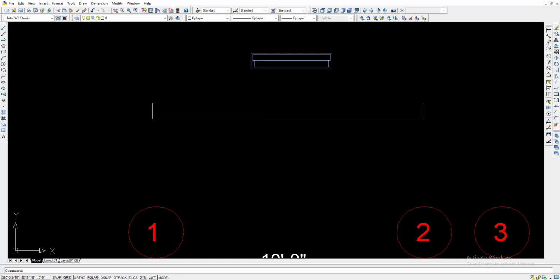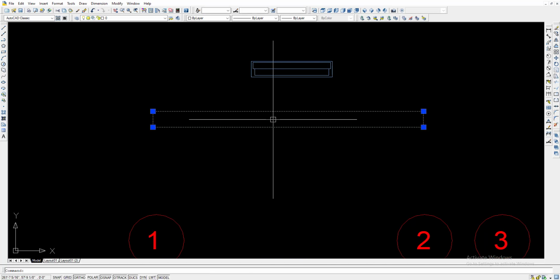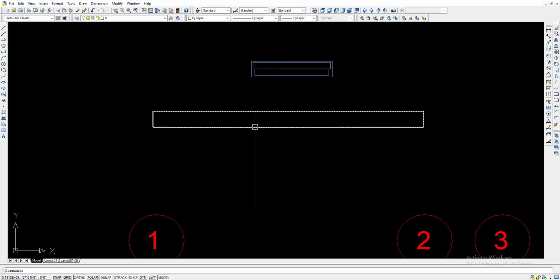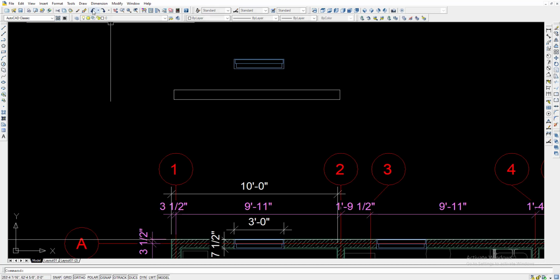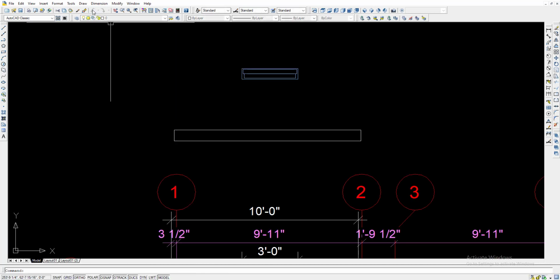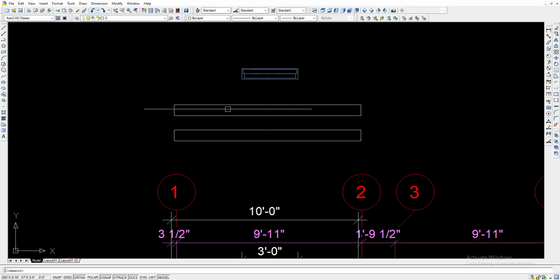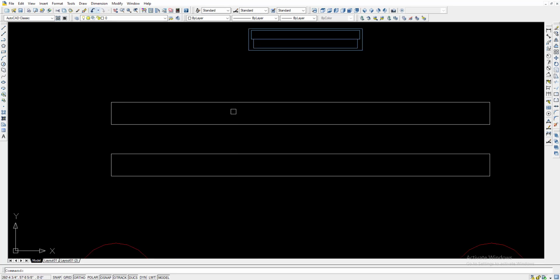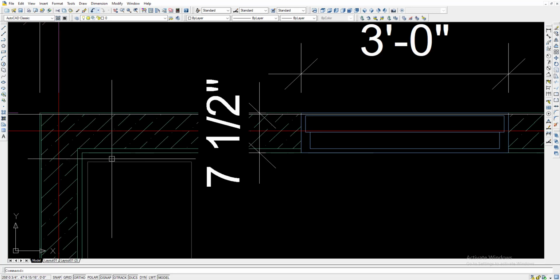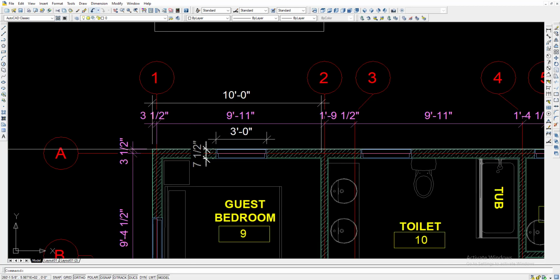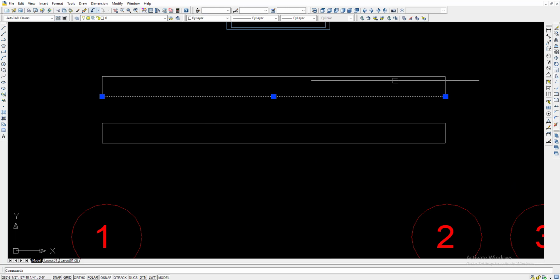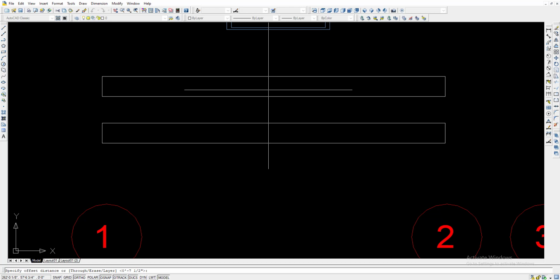But if I make a 1 inch offset, then all of my walls will be offset equally. Okay, then we can undo our previous one, right? You can see here our line. Here is the one offset from this line to this line. So we want to make this offset. Go to offset, and we are giving 1 inch here.